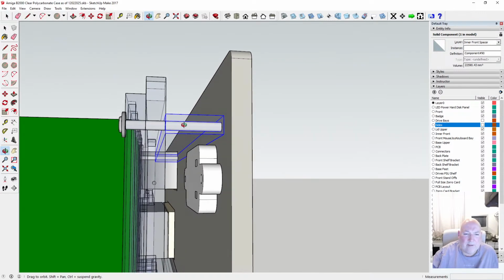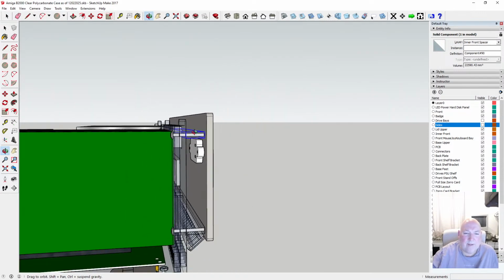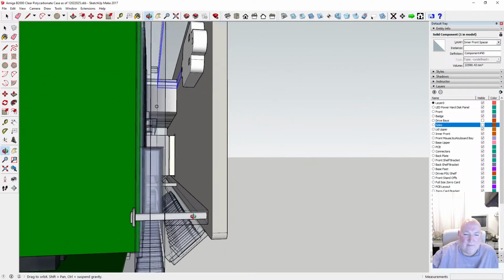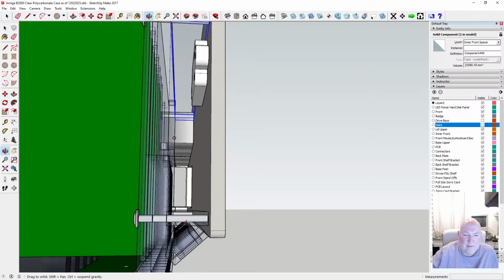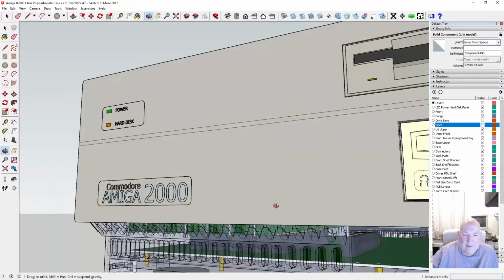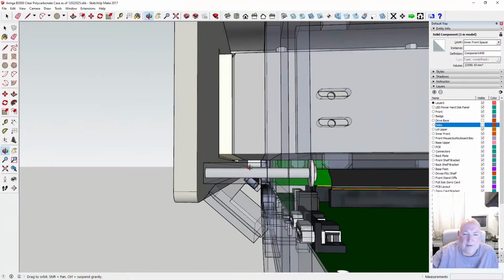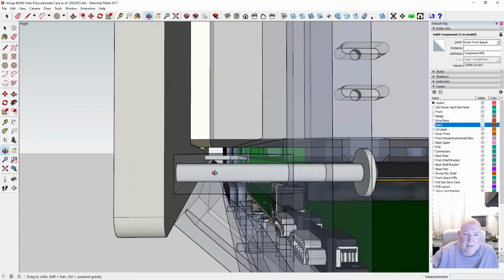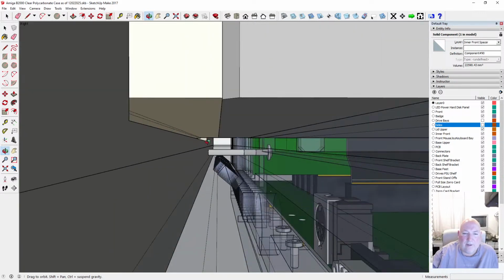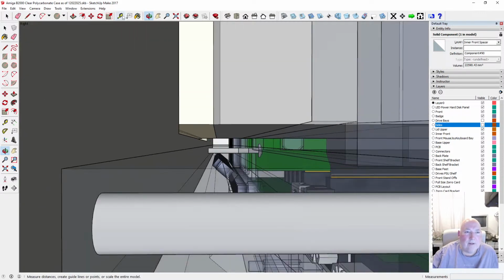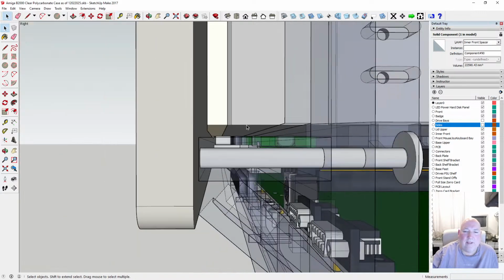So we could mill it, we'd have to make 2 bits and stitch it. And this long piece, now this might be the problem, because there's not enough clearance for 2 bits here. That's where it needs to go there, and you haven't got enough room here. So there's not enough room between this here and the surface of the component. Two mil is all you got. 2mm. So you couldn't do it there.